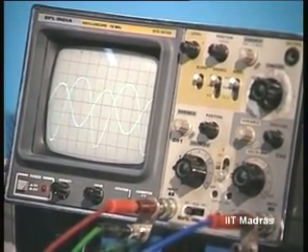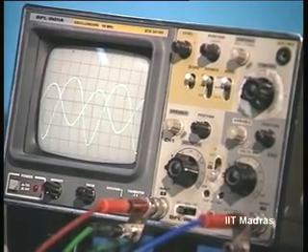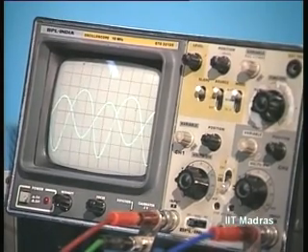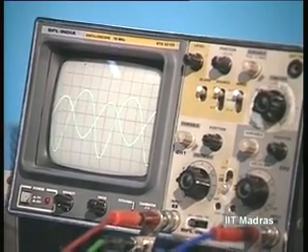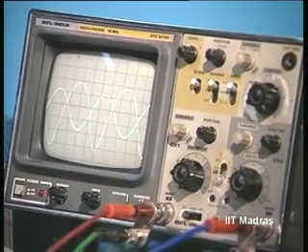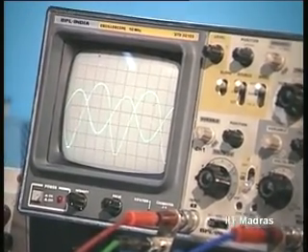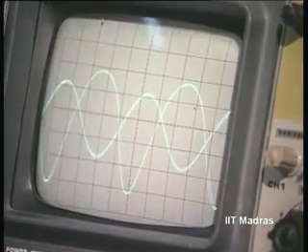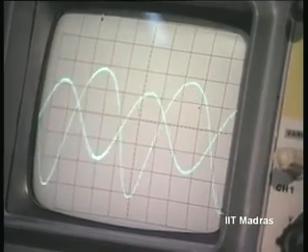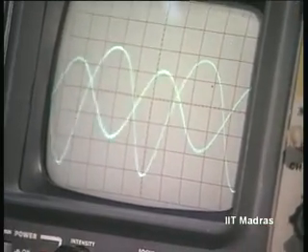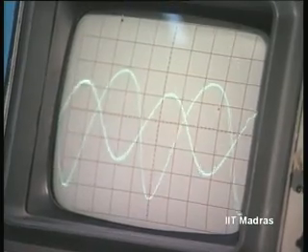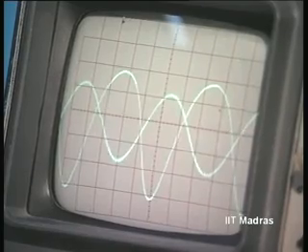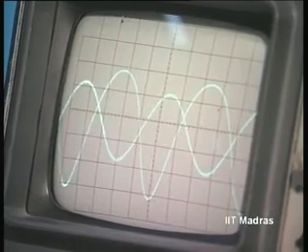Now please increase the signal level slowly. Just decrease it a little bit. You can see the lower portion going to saturation, and the upper portion corresponds to cutoff. So that is the signal limit. The signal swing comes out as, 1, 2, 3, 4, 5, very nearly 5, about 10 volts, around 10 volts or so. I mean, actually the signal can be further increased.